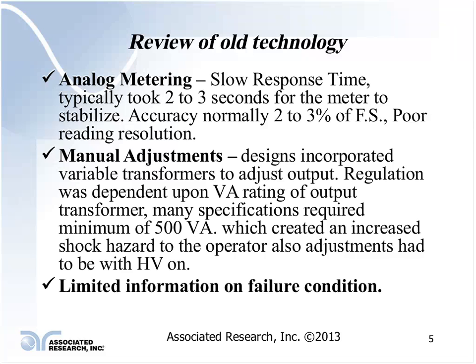So if you're testing at 1,000 volts, that's really over a 10% error that could occur at that setting. So, rather than a 1% or 2% of reading that is typically done now with a digital instrument, your accuracy is much, much worse with an old analog meter that has these type of accuracies.